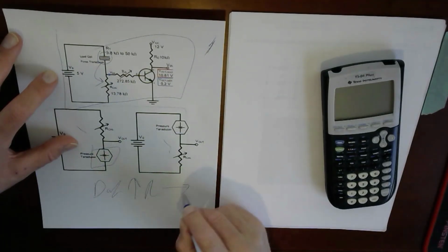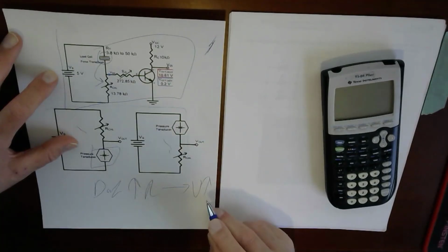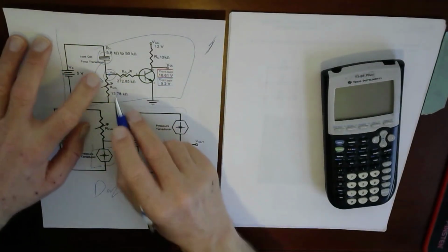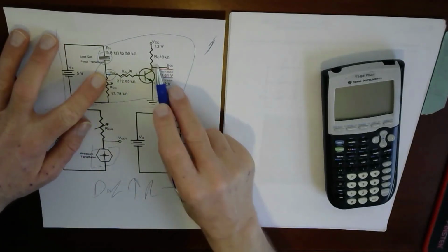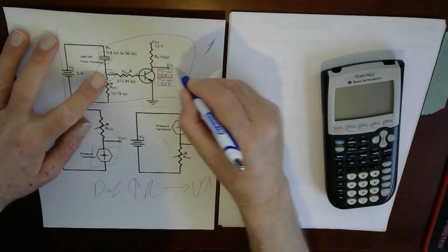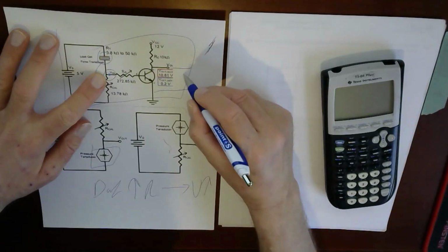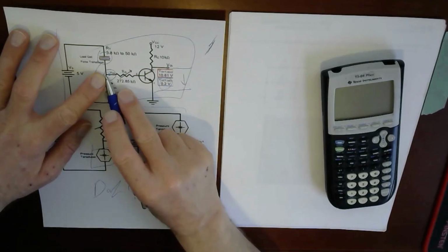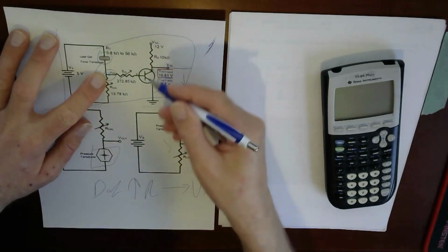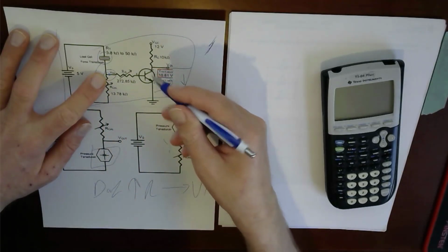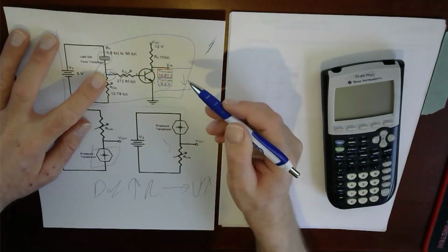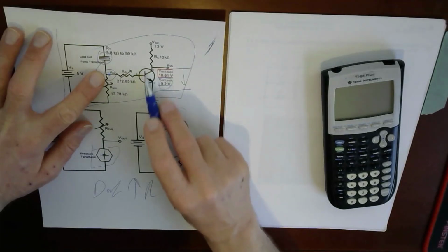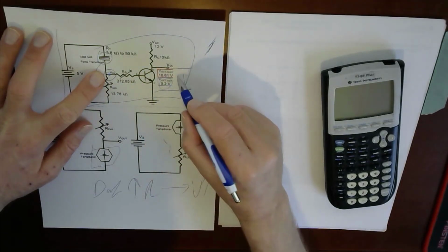It also needs to equal voltage high. The voltage has to be high when it's dark, because if the voltage there is at its highest, this becomes closed, and the voltage drop from here to there is going to be very low, 0.2 volts. Remember, when I have the most current through here, this becomes closed, and the voltage drop across goes to 0, or 0.2 volts. When this gets low, this slowly opens up, and my voltage here increases.